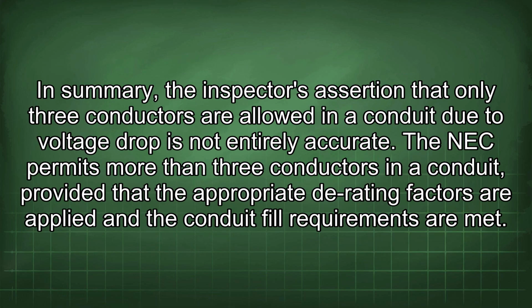In summary, the inspector's assertion that only 3 conductors are allowed in a conduit due to voltage drop is not entirely accurate. The NEC permits more than 3 conductors in a conduit, provided that the appropriate derating factors are applied and the conduit fill requirements are met.